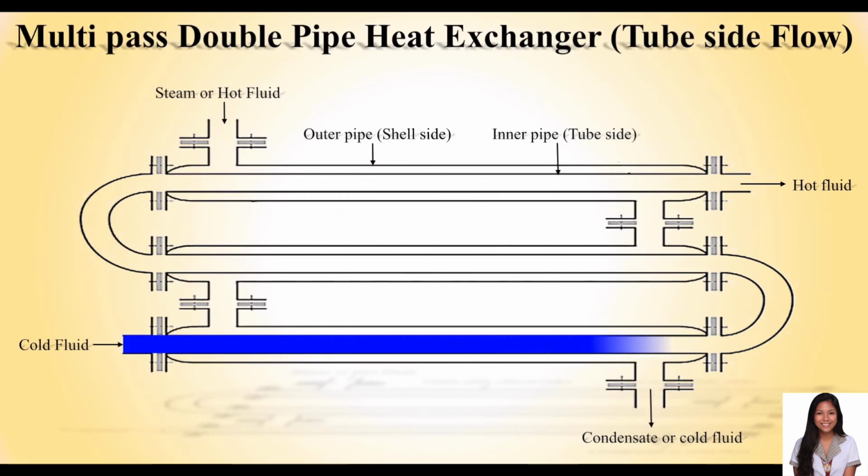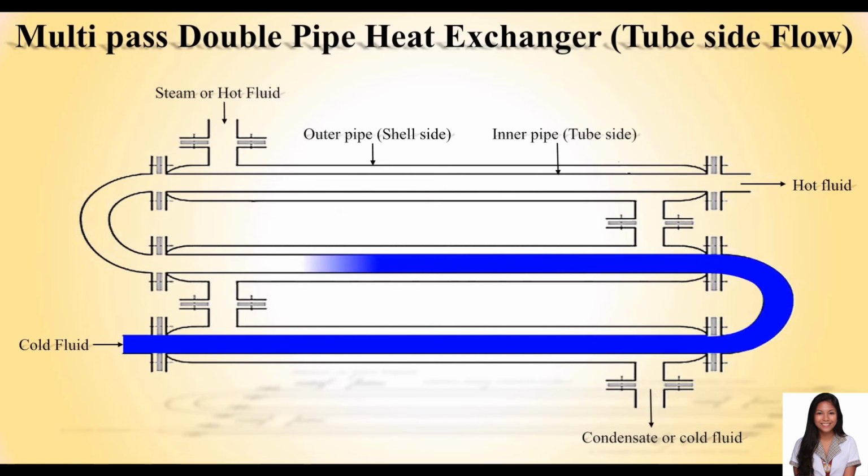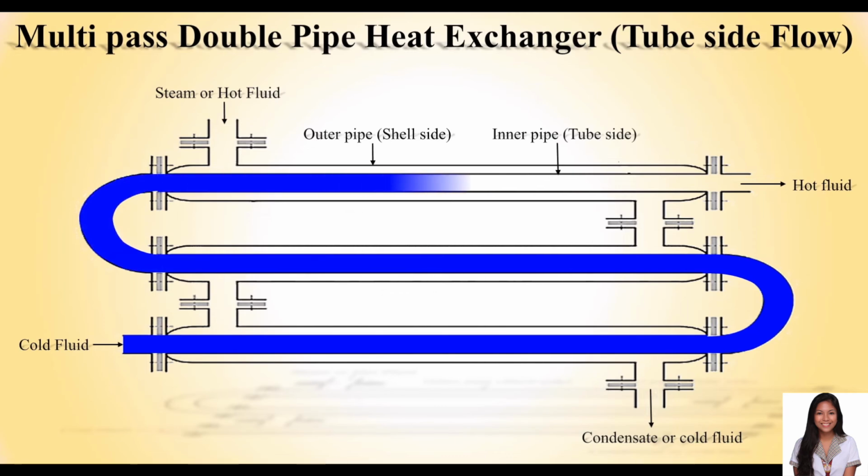bodies exchanging heat. While talking about temperature profiles of the two heat exchangers, this will only indicate two major disadvantages in the parallel flow design. First, the large temperature difference at the ends causes large thermal stresses, and the opposing expansion and contraction of the construction materials due to diverse fluid temperatures can lead to eventual material failure.